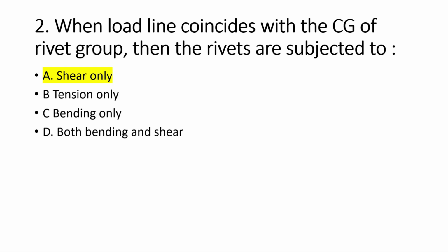So here you can see when your load coincides with the CG of the rivet group, that is your non-eccentric connection, then the rivets are subjected to shear only. So you have to keep in mind when the load is applied at the CG of the rivet group, the answer will be shear. So option A, shear, is correct. Move on to the next question.